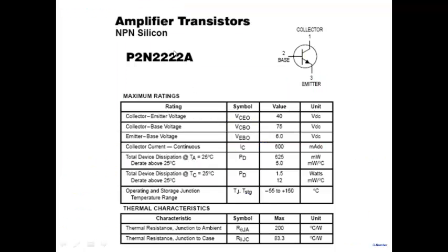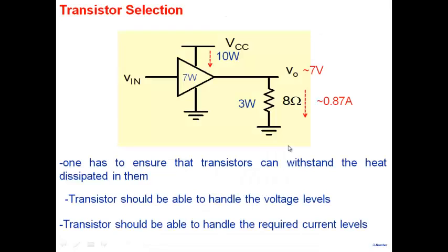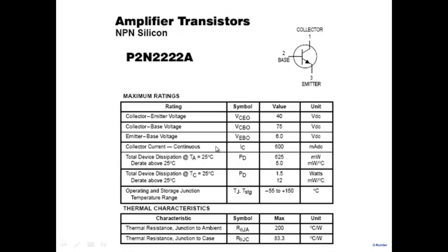As an example, if you look at this 2N2222 here, all the manufacturers will list for you the maximum rating of the transistor. For example, the manufacturer says here that the collector base voltage or collector emitter voltage is a maximum of 40. So 40, of course, is very large, will not bother you. Emitter base voltage is given here. Collector current, look at the collector current. It says the continuous value of collector current maximum is 600 milliamperes here. And this is saying peak current is 870, may not be suitable. You have to investigate in more detail because it's talking about continuous here.